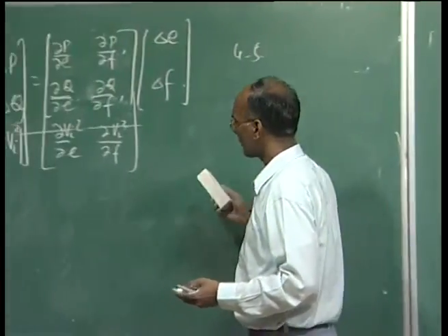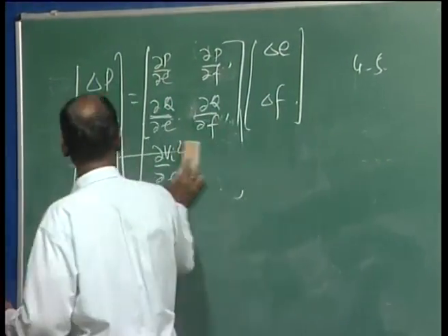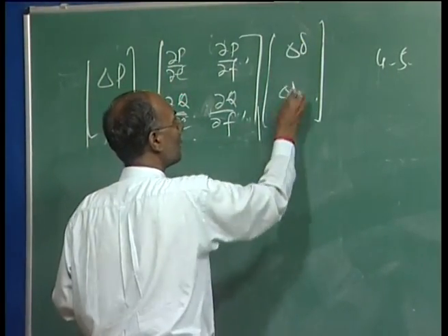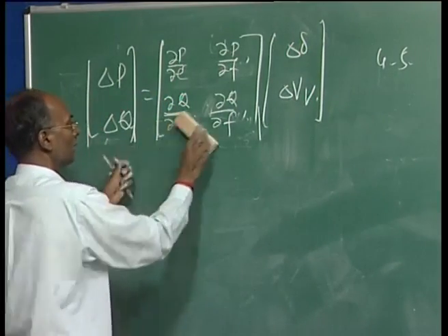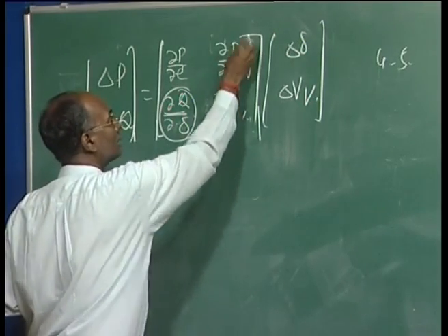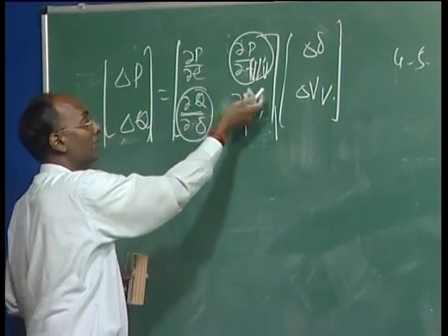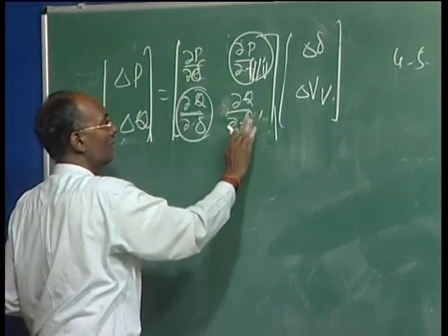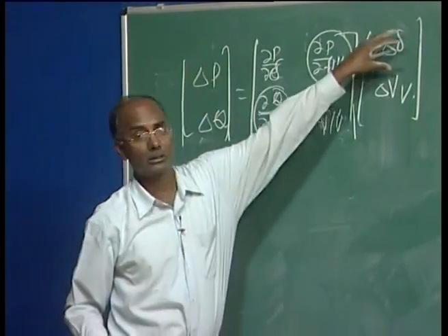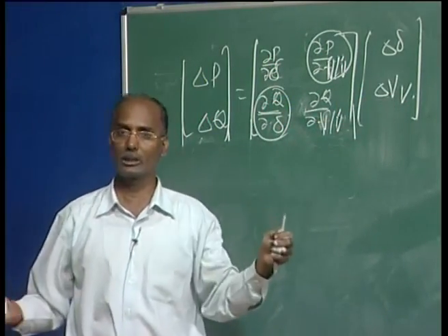In Newton-Raphson, in the polar coordinate, it was found that the off diagonal elements, now I can remove this, and I will use del delta here, del V upon V. It was found that this Jacobian and this Jacobian is very small. So, it was treated as 0, and then we can have the decoupled equations here. We can solve this is equal to this one directly, it is independent of this. Here this is only dependent on this. So, this is the decoupled equation.